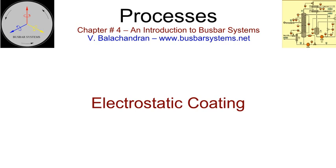The duration depends upon the size of the bus bar. The preheating temperature is recommended by the coat manufacturer. The preheated bus bars are introduced into the chamber for coating. The duration, discharge, and configuration of nozzles are controlled to provide a uniform coat of specific minimum thickness. The thickness of the coat to be applied depends upon the voltage rating of the bus bar.